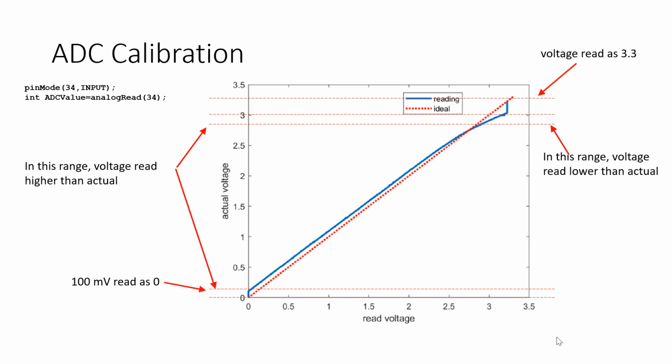So any voltage greater than 3 will be read as 3.3. So if the input voltage is 3 to 3.3, the ADC will just estimate 3, I believe, right? Because this line goes straight up. Make sense? You guys with me?